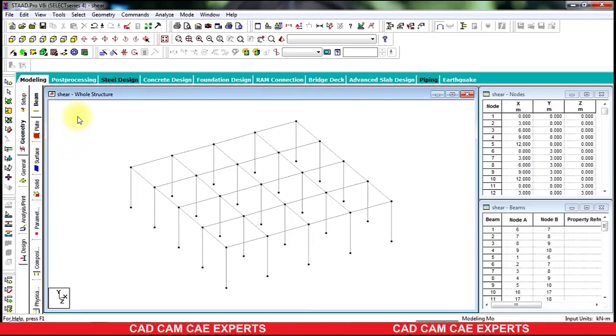So shear wall can be designed by using a surface element. So we will be selecting these two as surface element. You can click this, or else you can even click generate surface meshing and give two divisions. So let us select this. So in this way a surface is created for shear wall building.